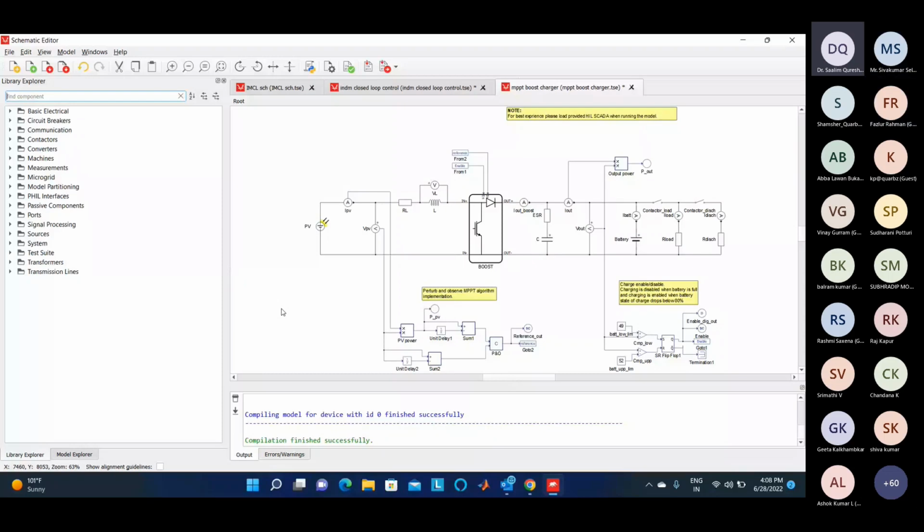You simply generate the C files with Embedded Coder and take only the three files, two header files and one source file, keep them in one folder, and call all these files as per requirement. You can try, and if you have any problem, you can connect with us. We will be there to help you out.